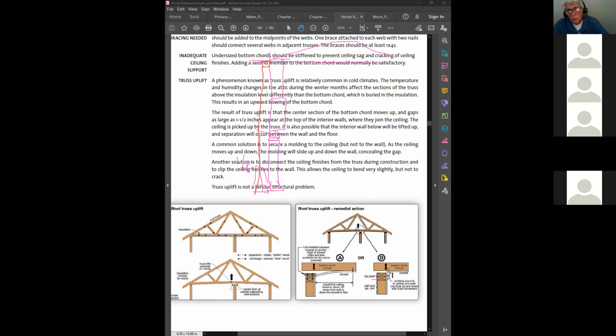So when the thing gets built, no problem. In other words, everything is nice. Now all of a sudden I have this brick wall on the outside that doesn't go under any moisture change. And I've got my roof truss here, and my bearing wall where the roof truss has gone down by 3/4 of an inch. So guess what's going to happen at the ceiling where the gypsum meets the wall? You're going to get the same problem. It's going to crack.